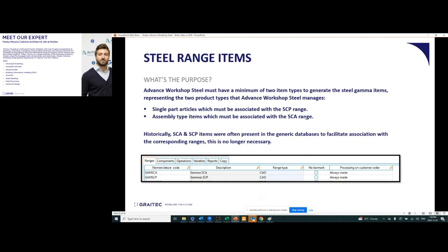So if based off of specific criteria, you would want a different type of part routing to come into effect for that specific type of assembly, or if it had a special paint coating, if you wanted additional operations to be applied and costs to be compiled, we developed features to be able to enable this upon import, as opposed to then having to manage it later on in the customer order in a more manual method. So there's a multitude of ways that we can manage import of data now with steel parts and assemblies through management of scripts and manufacturing sequences.